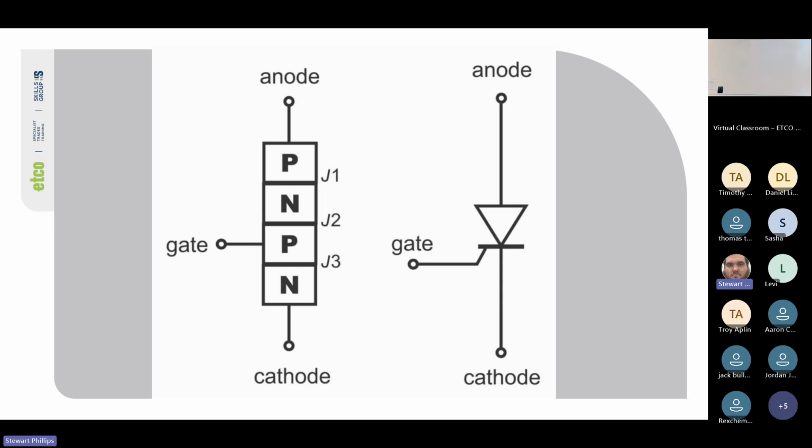As we apply the holes to P and the electrons to N, they will move towards the middle, but because the P in the middle is not activated, it will not allow it to conduct. But once electron flow has started moving, it will continue until we completely stop the current flow. So yeah, it is a latching relay type device.